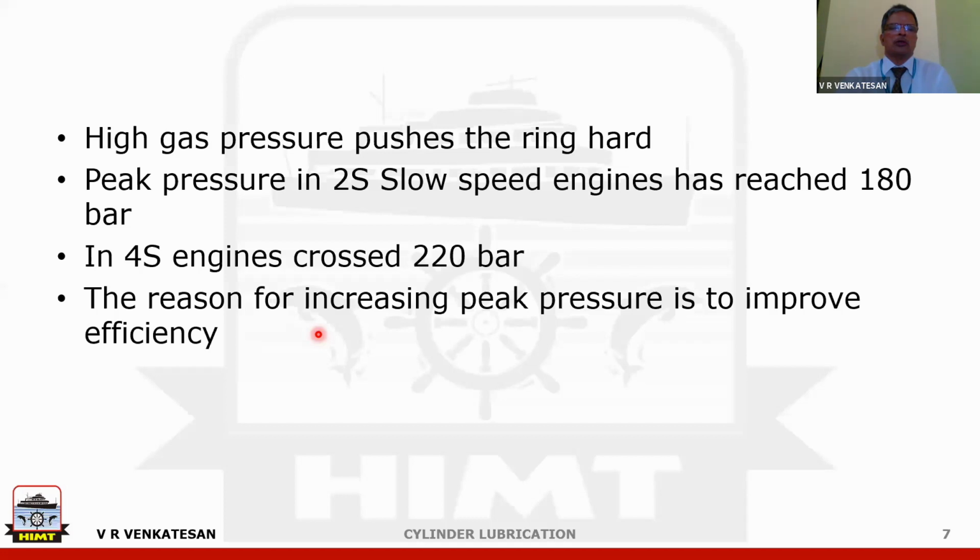So the way to understand is, if you can make MEP more, it will improve your power to weight ratio, or what we call specific power. Power to weight ratio will be more if MEP is high. But if you increase peak pressure, then the efficiency is more. The reason for that is from the principle of engine functioning.